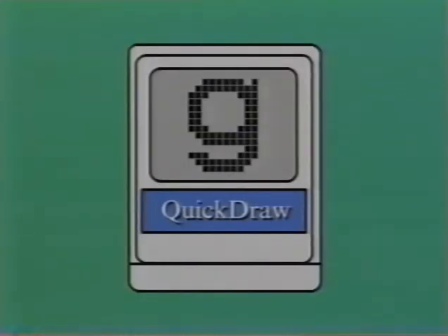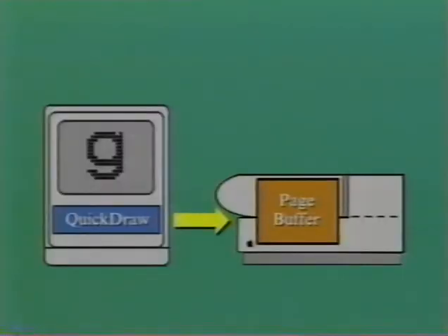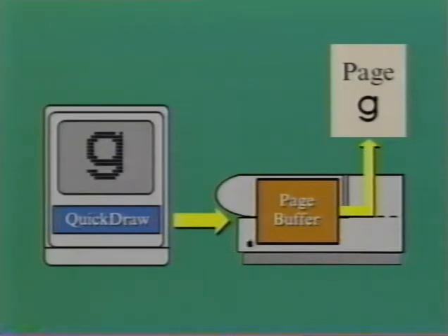In the Laserwriter 2 SC, the printer resource resident in the Macintosh operating system sends the bitmap image directly to the page buffer in the printer. Because the image is a 300 dpi page, it uses a considerable amount of data. A SCSI connection makes it possible to transfer this large amount of data at high speed. Once the data is stored in the page buffer of the Laserwriter 2 SC, it is already described as a 300 dpi image, and it, therefore, requires little processing to transfer it directly to the hard copy page. This is the QuickDraw process of printing.